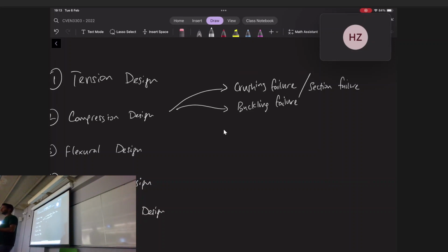Which one governs? The 200? Why? Because you see that it takes more force. Let's run that thought experiment. I picked that thing up now physically, right? I know at 150 kilonewtons, if I pull it apart at 150 kilonewtons, it'll fracture. Wait, no, it has to be less than 150. Exactly. Yeah. Right? It's the other way around. So that's the thing you've got to remember.